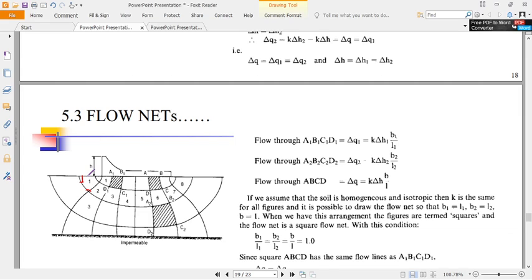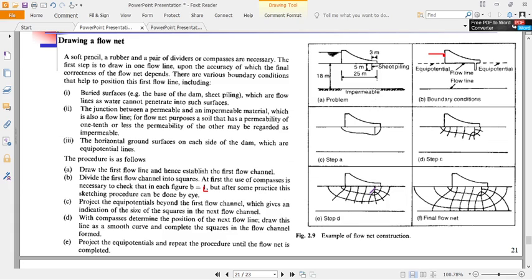After doing these equal potential lines, mind you, this is a flow line. So you can come and join this to produce this equal potential. Remember, this is a flow line, and from a flow line you can draw an equal potential line. Remember, the equal potential has to meet the flow line at 90 degrees. You have a flow line here, so this line should be projected as you draw, making sure they meet the flow line at 90.